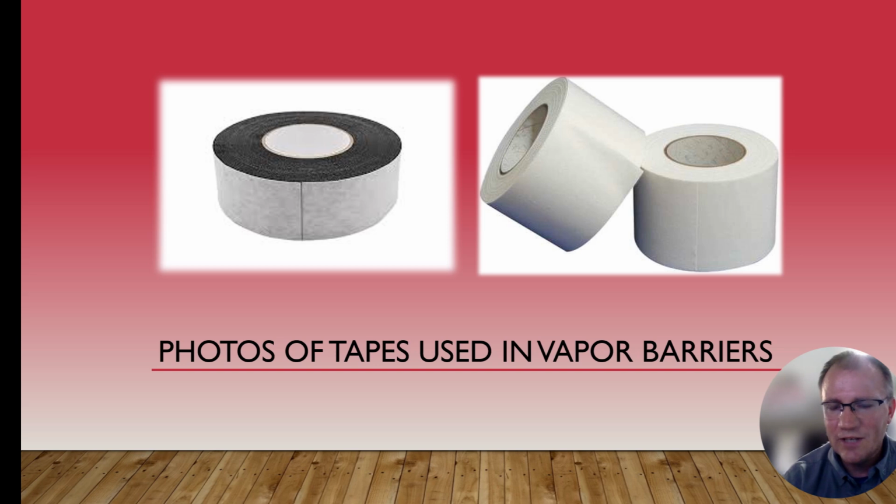You can also see the 6-inch wide white seaming tape here. That's really good for everywhere on the floor. When you cut your vapor barrier and anchor it down, you're going to have seams, and you need to run this tape down every seam. Once again, what I'm showing you is in white, because I really like white for vapor barriers or crawl space encapsulations. That's up to you if you want to use black or another color. But at least this gives you an idea of what those materials look like and how you're going to use them.